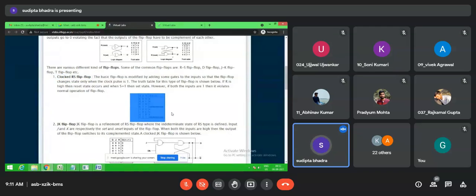Now here in the third truth table, the Q state is represented with respect to timestamp. At timestamp t, this single flip-flop can be taken as a single memory cell, where the output Q is representing the current state. So here the Q is 0 and the SR is 0 0, then Q(t+1) is also 0. It means the state is not changing.